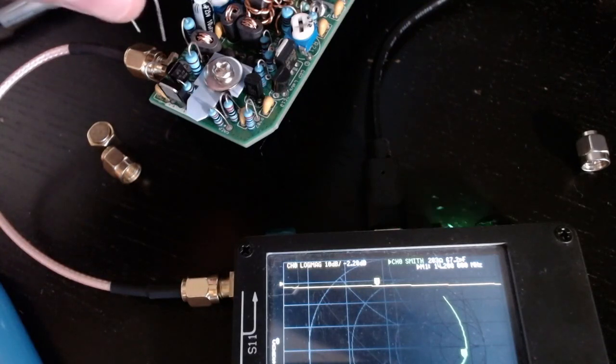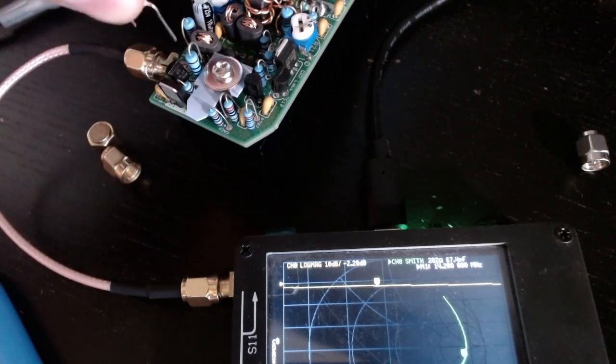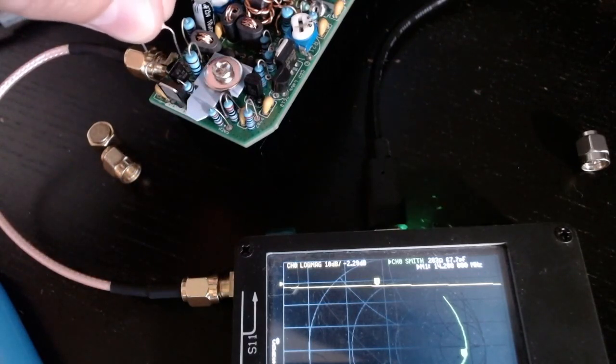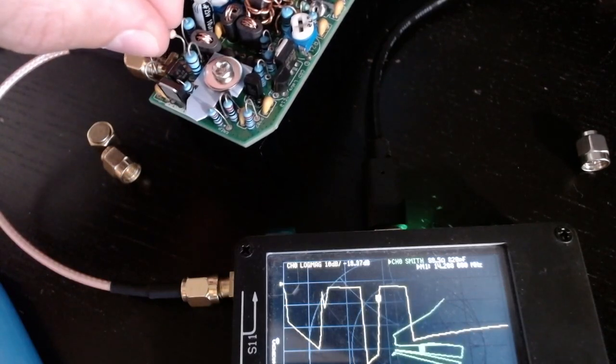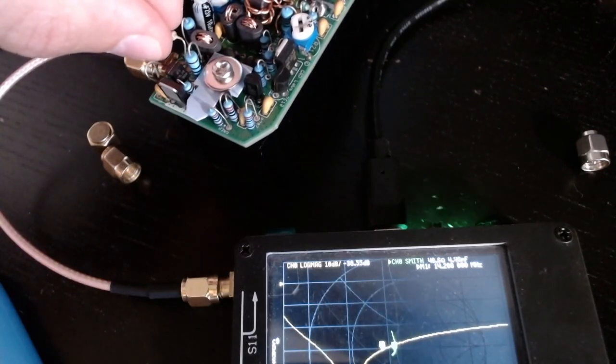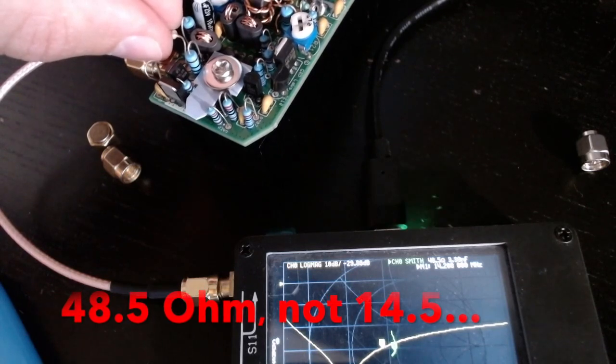Okay, so look at what happens when I short this. I simply put a resistor in parallel here with the input. Manually, so that's not an ideal thing to do, but just to check what happens. So as you can see now, the return loss is reading minus 30, which is excellent, and the impedance here is 14.5.